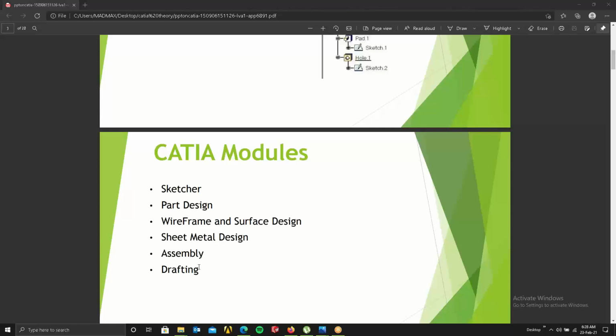Then you have the Part Design workbench. But one more thing to remember in Sketcher is selecting the planes. Selecting planes is very important. Some people just take random planes and start sketching. You should observe the model first. Whatever drafting you have at hand before 3D modeling, take a few minutes and study it and see which is the easiest way in which you can do that model, so that you don't waste your time.